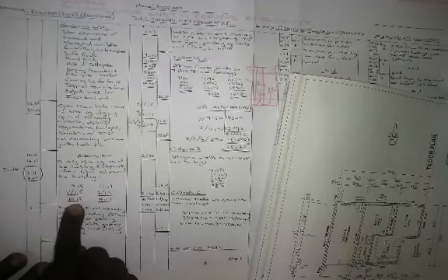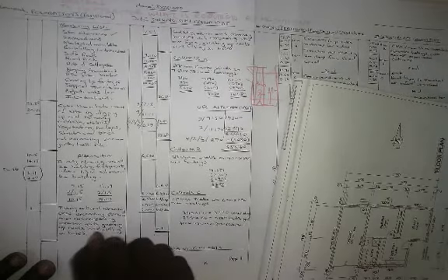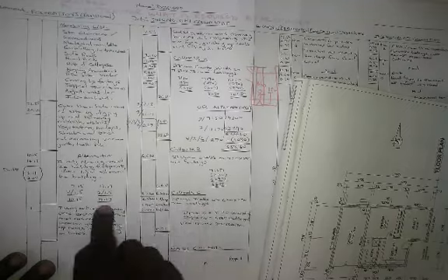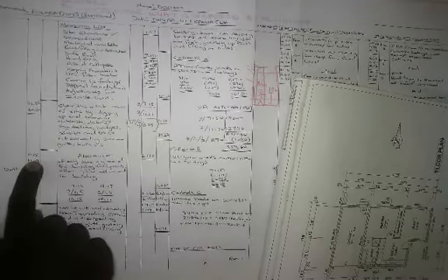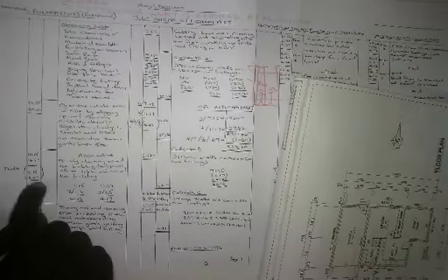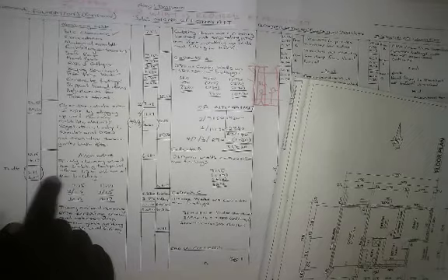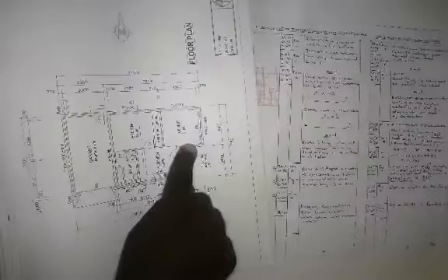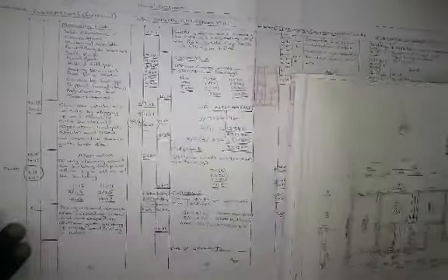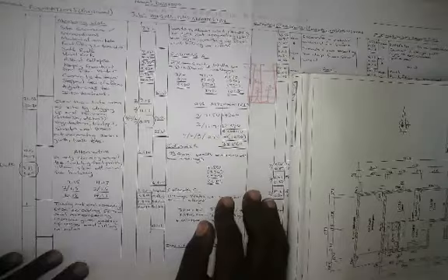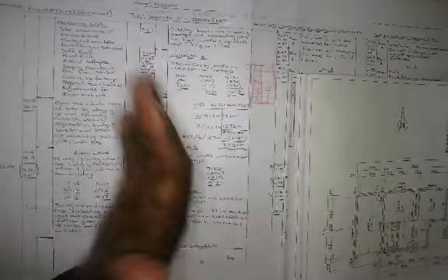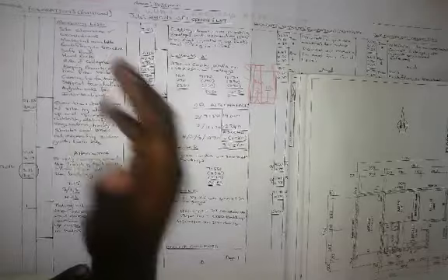When you add 1.5 on both sides of 7.15, you get 10.15. When you add 1.5 times 2 at 11.17, the longest length, you get 14.17. You take that, you put it in your times column, and then you need to deduct that area. It's almost like a return or a recess, the L part of your drawing. This part, you need to deduct. This is not a square, this is not a rectangle, so you cannot over measure that piece. Okay, guys, fine.